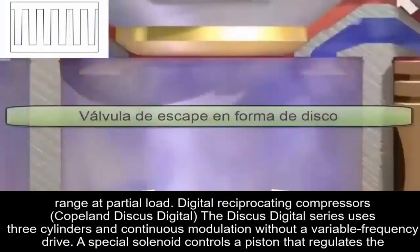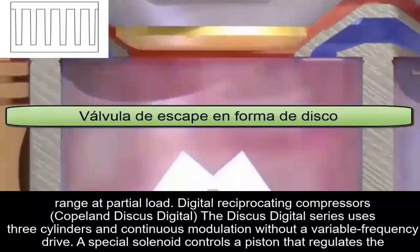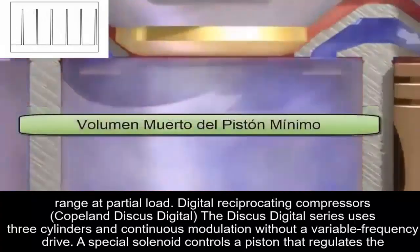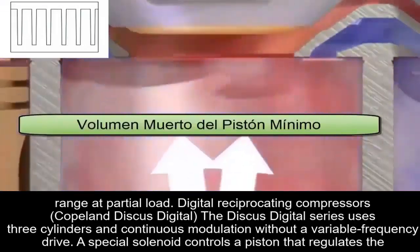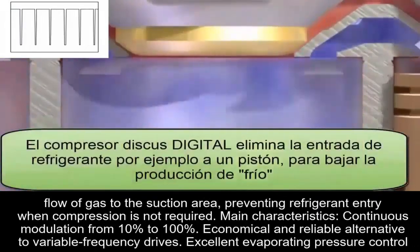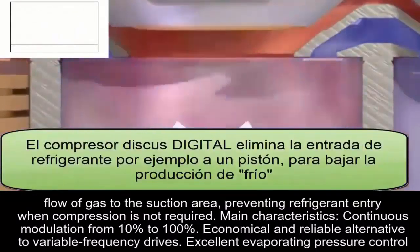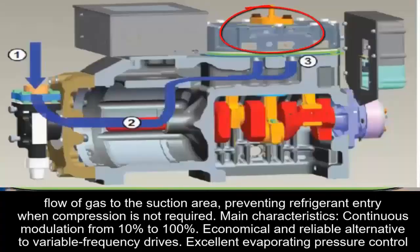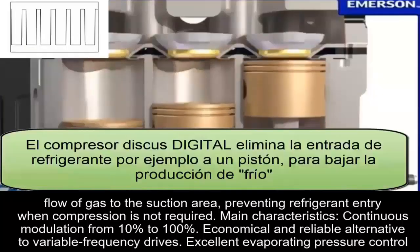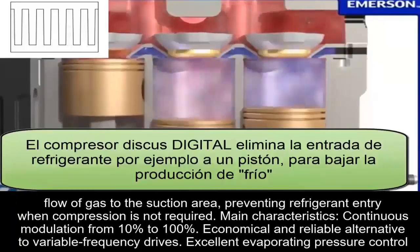Digital reciprocating compressors, Copeland Discus Digital. The Discus Digital series uses 3 cylinders and continuous modulation without a variable frequency drive. A special solenoid controls a piston that regulates the flow of gas to the suction area, preventing refrigerant entry when compression is not required. Main characteristics are continuous modulation from 10% to 100%, an economical and reliable alternative to variable frequency drives,